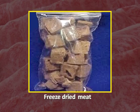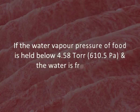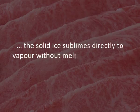In freeze drying, the water content is first converted to ice and then changed into vapor without passing back through the water phase. If the water vapor pressure of food is held below 4.58 torr, that's 610.5 pascals, and the water is frozen, the solid ice sublimes directly to vapor without melting when food is heated.